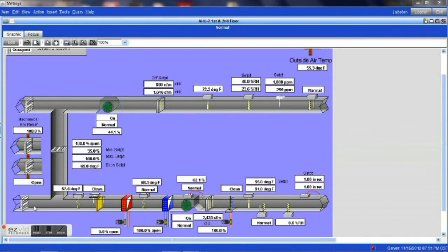So when we bring air into a building like this, we also have to exhaust out a specific amount of air as well to keep the building from going too positive. That can cause your doors to stand open and a lot of other issues. This mixed air section here will basically control the amount of air that is returned to the supply fan section to be reused within the building, and/or to exhaust out the excess pressure if we are economizing.